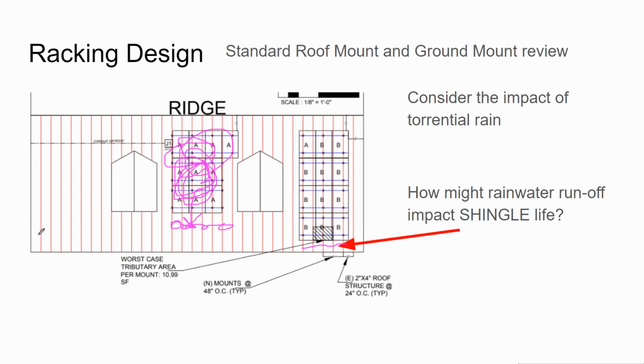And so now what I do with my designs is try and start them so that the rainwater runoff is going to slide off the modules and hit the gutter, rather than stopping the array closer towards the bottom of the roof. At the same time, I install in areas where there's more rain and snow doesn't really exist.